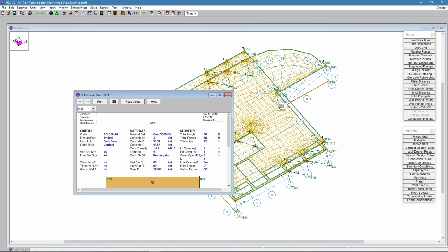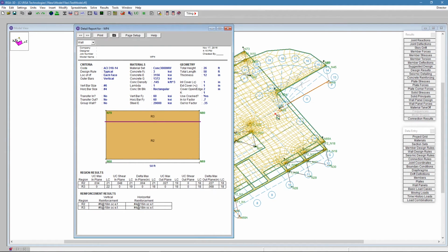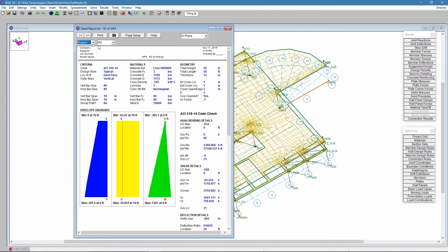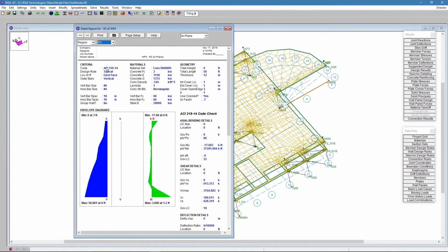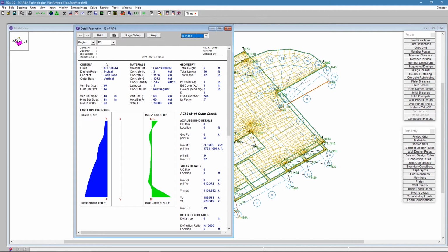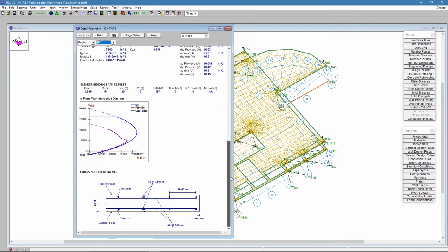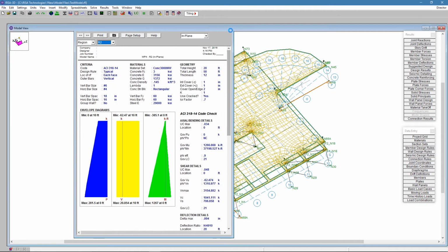If we look here, we can see some of the information for our parapet. I want to show you, this was the concrete parapet wall that we added on this lower portion here. And we can get design information on the R2 and R3 regions. So that's the upper portion of that. If you looked at the upper portion, this was the parapet loading in plane and out of plane. You can see how that's being added into the model here for that R3 versus if we're looking at R2, which is the base of the model. So it's designing that concrete wall for you there.